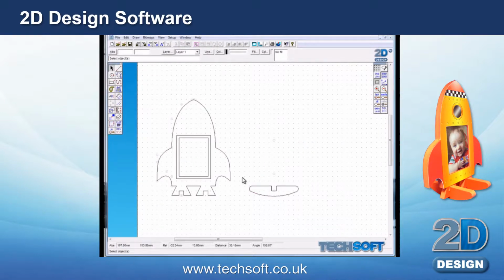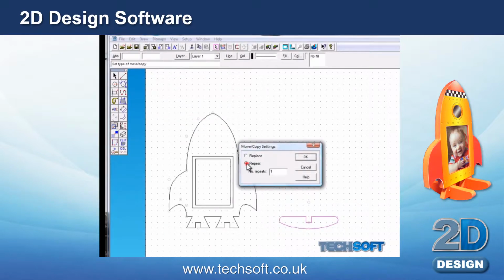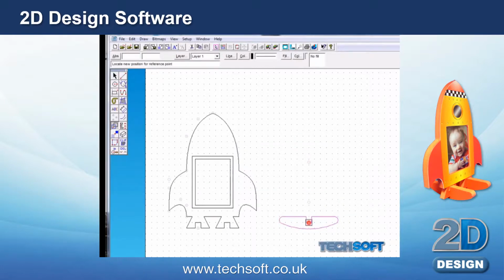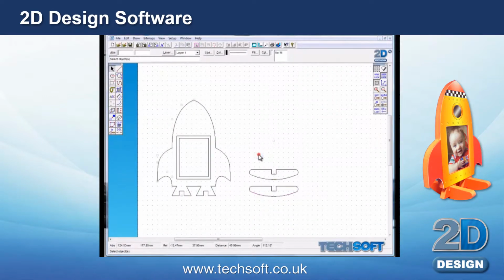We'll now need to copy that because we need two. So we select all, transform, we want to repeat, we only need the one, and OK. Join one construction point to the other, I'll just drop another one in. Another way of copying would be to select whatever it is that you want to copy, select the copy icon down the bottom, and then drag it over.